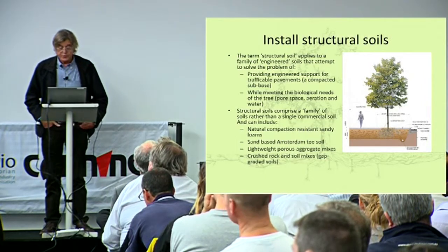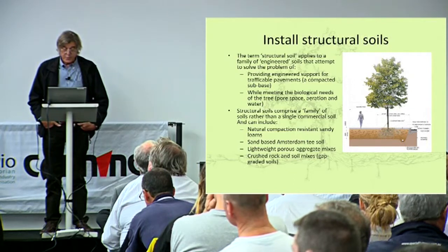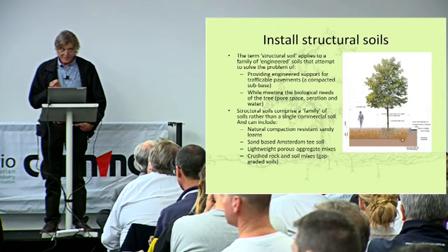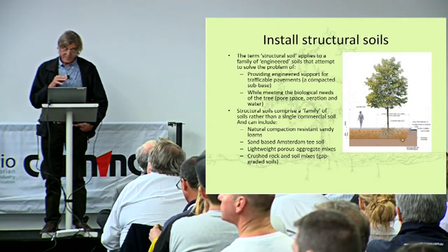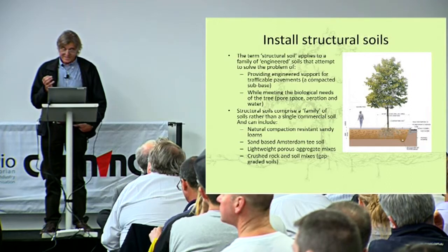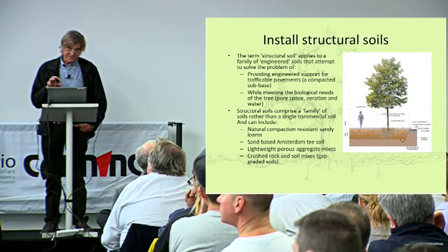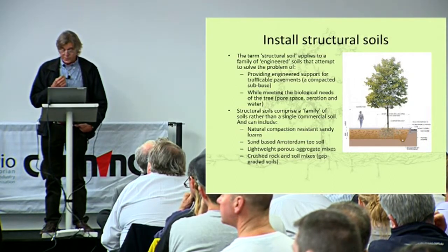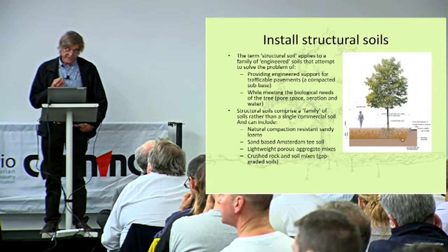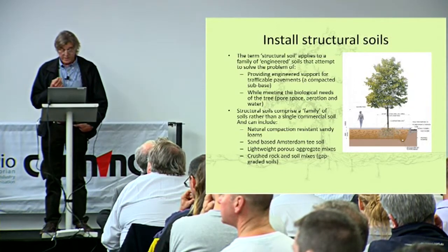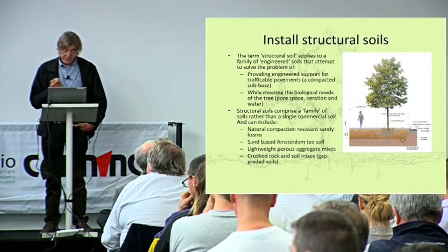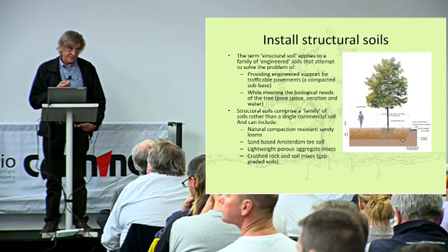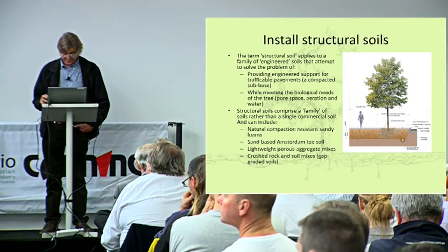The other option is to install structural soils. The term structural soils applies to a whole family of engineered soils, not just one soil type, which attempts to overcome that problem of how do you provide engineering support for pavements at the same time as meeting the biological needs of trees, which is to grow in uncompacted soils. And structural soils comprise a family of soils rather than a single commercial soil, including natural compaction-resistant sandy loams, sand-based Amsterdam tree soils, lightweight porous aggregate mixes, and crushed rock and soil mixes, which are known as gap-graded soils, which are the ones you read most about.